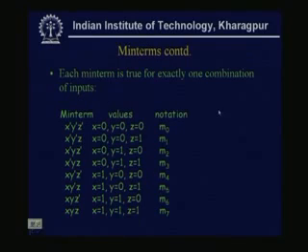Now, already we have seen that if these are the min terms, what do we mean? Last day we discussed the convention: if x equal to 0, y equal to 0, z equal to 0, that means a literal that is 0 will be complemented. So, x prime, y prime, z prime, or x dash, y dash, z dash, means the 3 variables are zeros, and the decimal equivalent of these values is the subscript. So, this becomes m0. Similarly, we can do this.